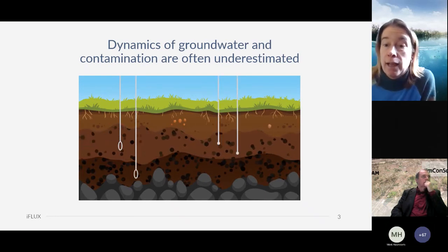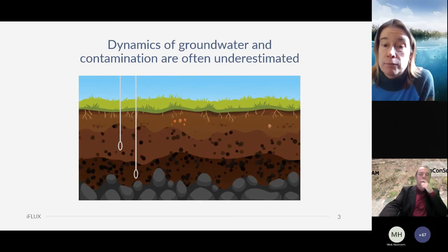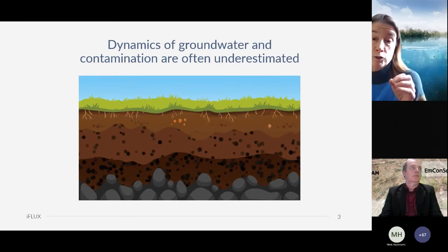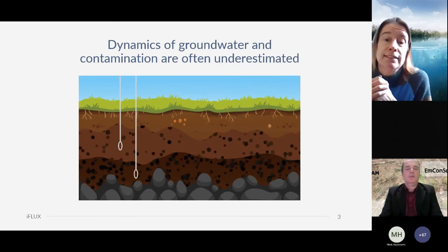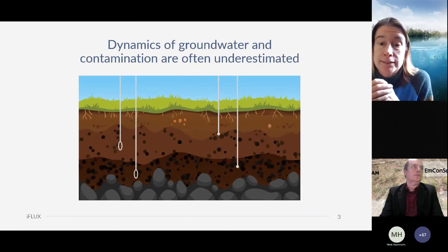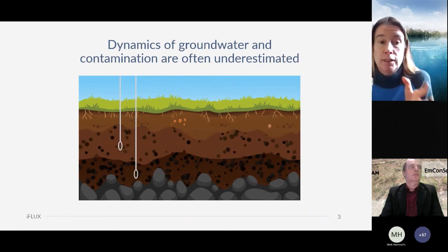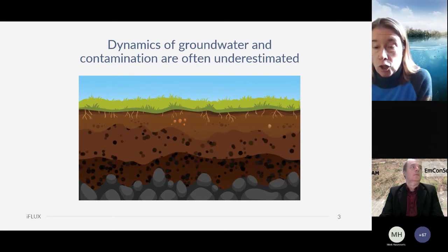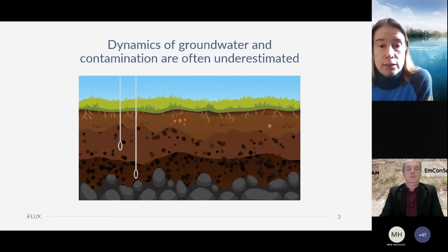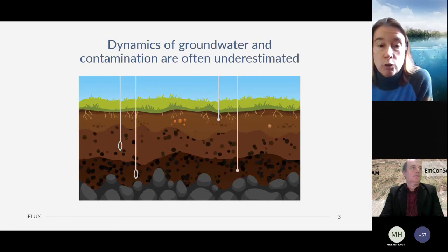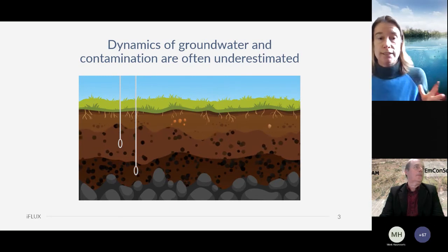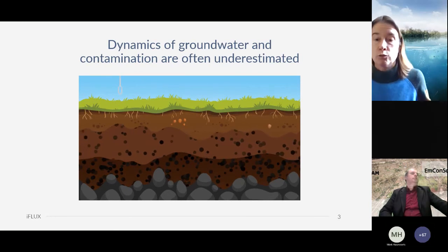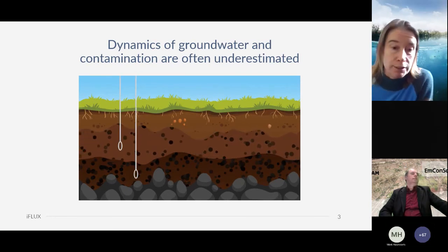For PFAS contamination, where the concentrations are very low, but also the standards are very low, in nanogram per liter scale, the external influences can be very important and they will influence the results. So therefore, I think it's very important to look a little bit further than only the conventional low flow sampling and to measure over a longer period to have more reliable and stable results.